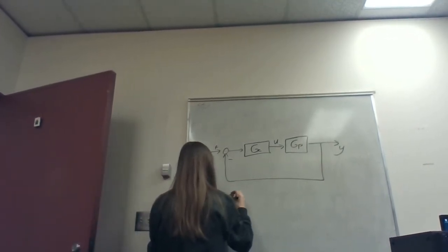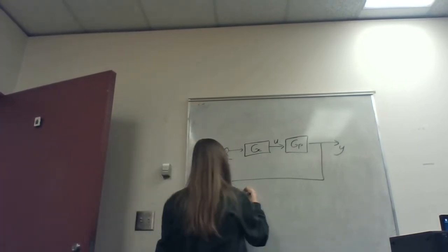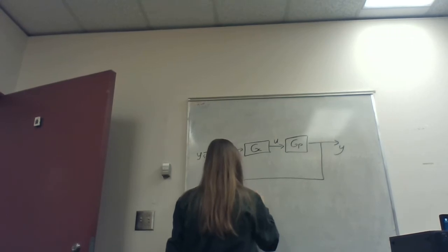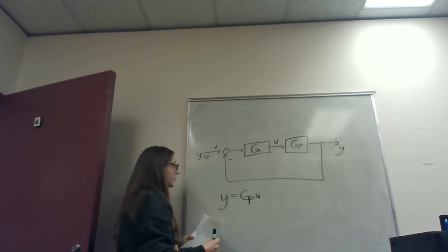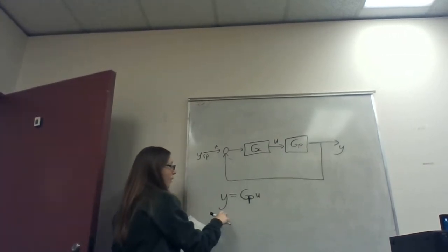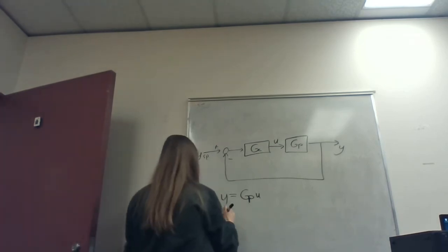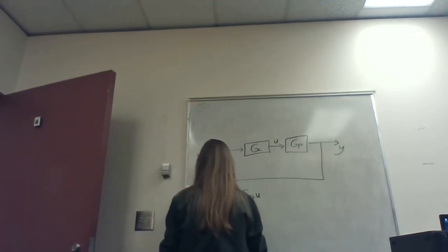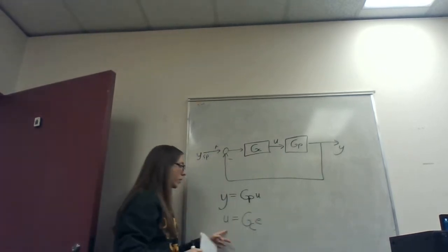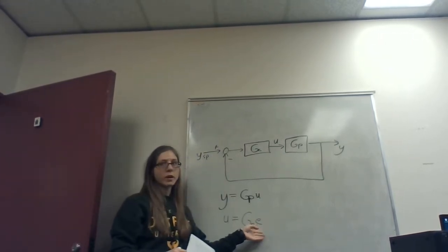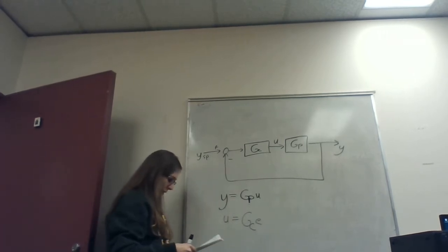Here, the way that we model our output is that this block diagram is reflecting G times u, so that essentially the derivative of the output is related to the inputs. If we go back out of the Laplace domain, here's the controller transfer function. So the control action is the controller transfer function times the error.